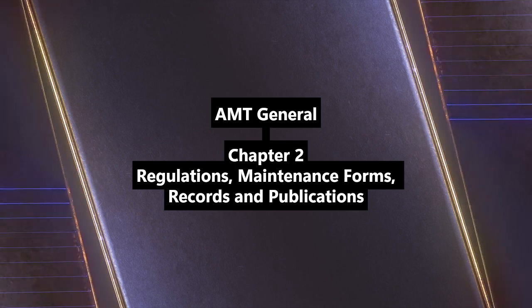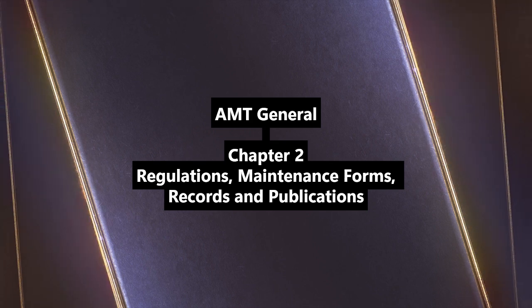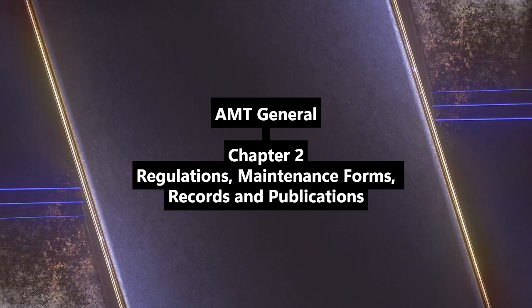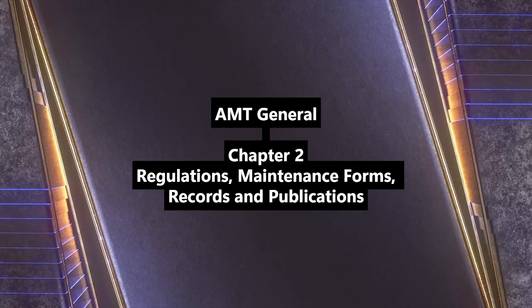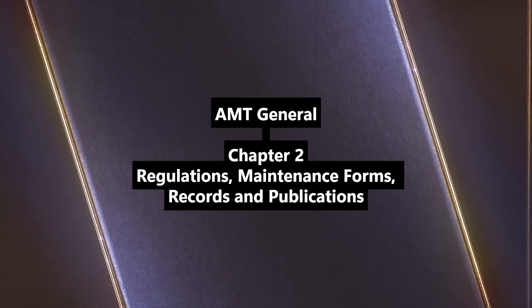No operation without an airworthiness certificate, which requires meeting the TCDS specs. Categorized by holder product type, revised as needed, like the Beech King Air TCDS A24CE example.